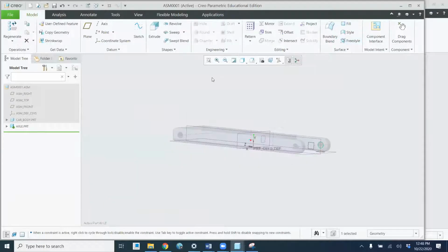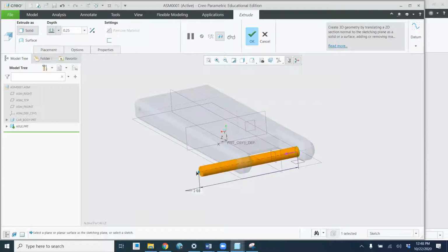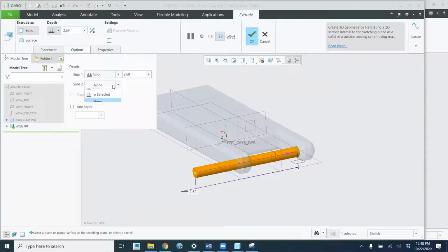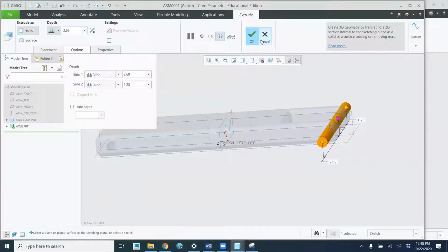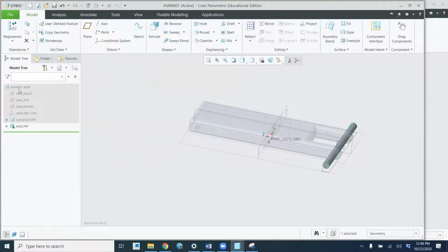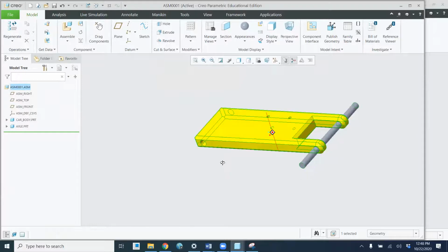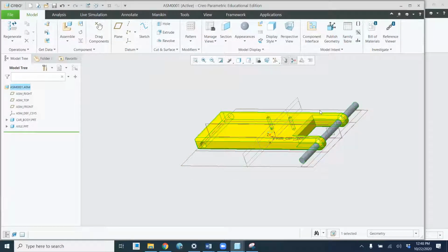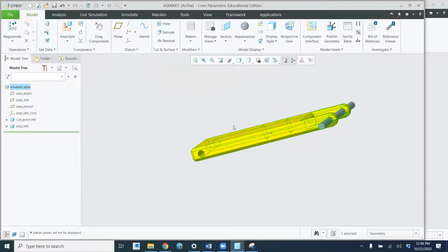And now I can extrude that. Maybe I'll extrude it this far this way, and then we could do another out the other side, something like that. Okay. So I can check mark that. And that is my new axle part. Now, if I go back up to the full assembly up at the top and activate that, now I have this two-part assembly, which has both the car and the axle going through that. Let me turn off the...